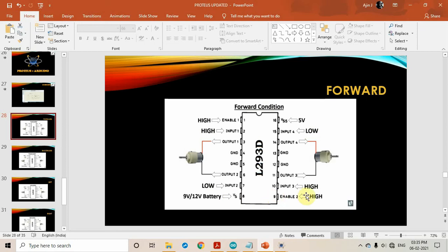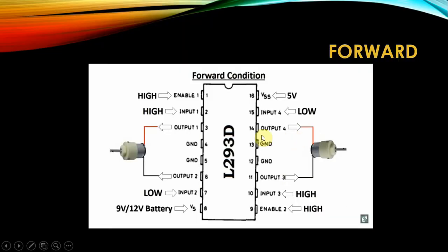So for this, we need some kind of driver, that is a motor driver, and the commonly used one is the L293D driver. By applying high voltage at different positions of this chip, since they are connected in such a way, we can rotate the motors forward as well as backward without switching the wires. So that is one application where we need a motor driver like the L293D.